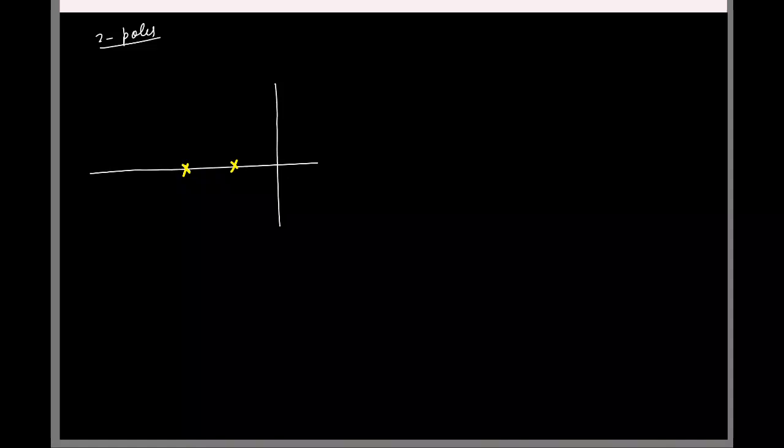Cool. So now let's increase the complexity. Let's say I have two poles now. So again, as I change A naught from 0 to infinity, the closed loop poles will start from these and go to minus infinity. So here I'll just say one more rule. It turns out if the root locus has to lie on the real axis, what is the condition? Do you guys know?